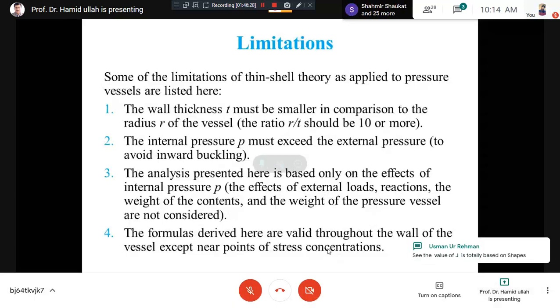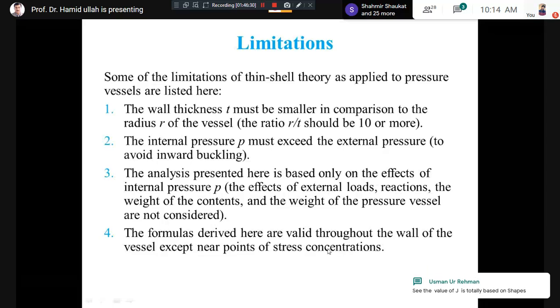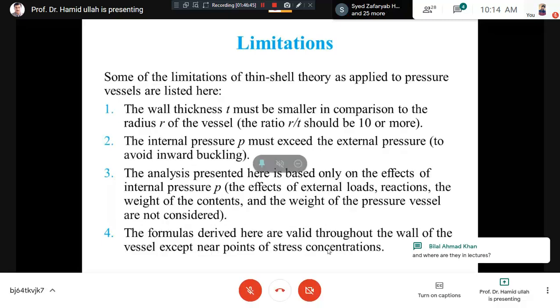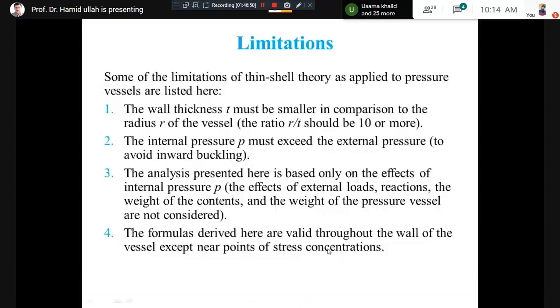Another is the step shaft. अगर आपके पास एक शाफ्ट है जिसमें कोई स्टेप नहीं है, यानी यूनिफॉर्म डाया शाफ्ट, तो स्ट्रेस कंसंट्रेशन नहीं होगा। बट इफ यू प्रोड्यूस अ स्टेप शाफ्ट जिसमें दो पोर्शन हो, एक पोर्शन का डाया एक हो और दूसरे पोर्शन का डाया अलग, तो फिगर में बताए अनुसार there will be a step. That is called a sudden change in cross section, because from less you change to more dia, and in other words from more dia you change to less dia at some point.